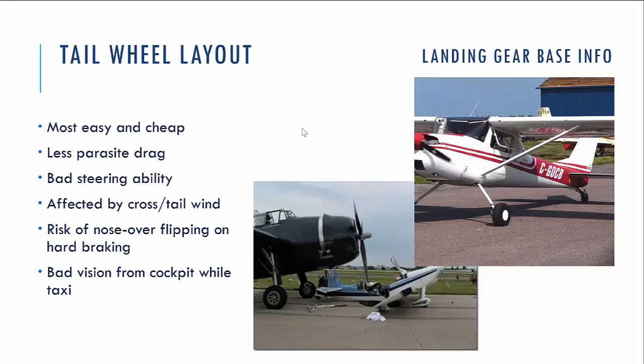And also because of the lack of support in the front part of the airplane, there is a risk of nose over, flipping the airplane on hard braking, for example on landing. And there is one more problem with the vision from the cockpit. In this kind of airplane, you won't see anything from the pilot seat.